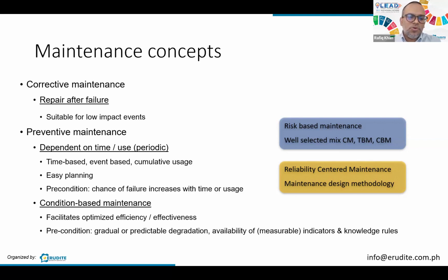So with CBM, there is also one part which is nice. It allows the asset owner to defer maintenance. Sometimes you think that, okay, the asset is doing well, but we don't need to do it so soon because we have not used it to the maximum loading, for example. So you can defer, based on the condition, maintenance to another time. Saves you money, saves you time.